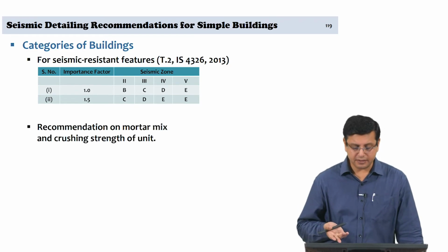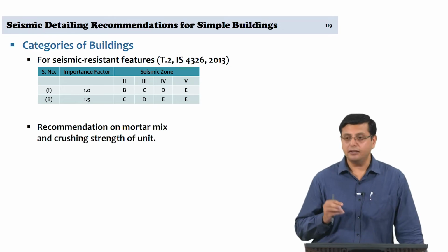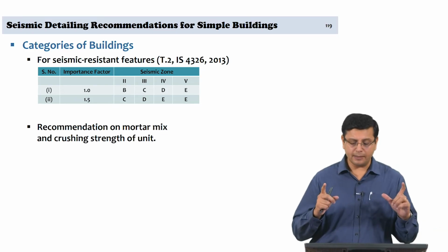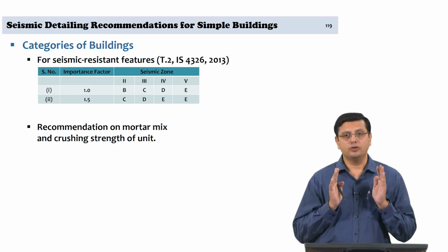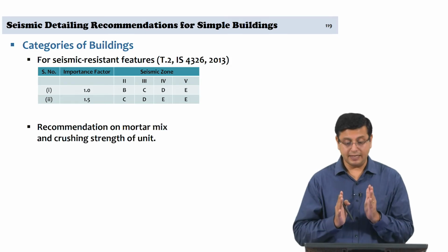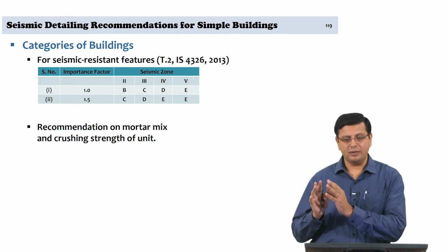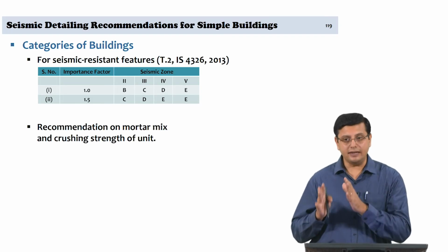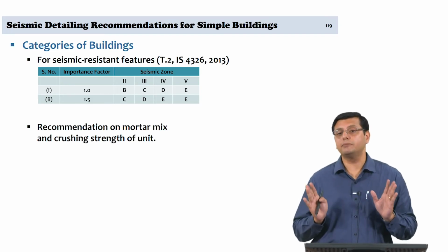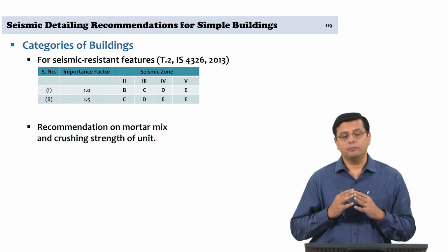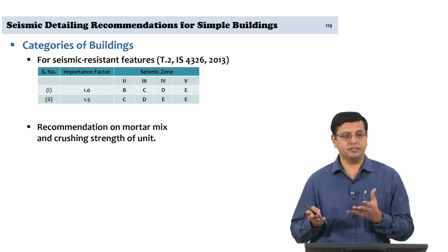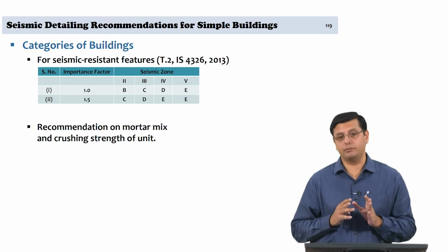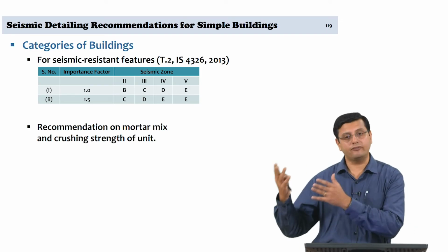So, one of the first requirements is on the mortar mix that can be used, such that the whole concept of a simple building is you are not going through rigorous structural design calculations, and therefore, you must have a minimum set of construction features in it such that you expect desirable performance under an earthquake. If you were to look at complex configurations, you cannot be sure that these requirements alone will take care of desirable behavior, and that is the reason why those structures have to be designed.